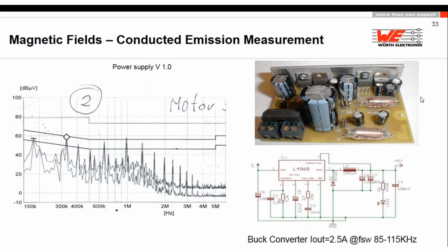It's a dual layer PCB. We had the idea: please change these two inductors to shielded ones, flood the top side with ground, and make vias to have a good ground plane, and try this again. He goes back to the EMC lab. The EMC lab looks at his schematic number one, schematic number two.